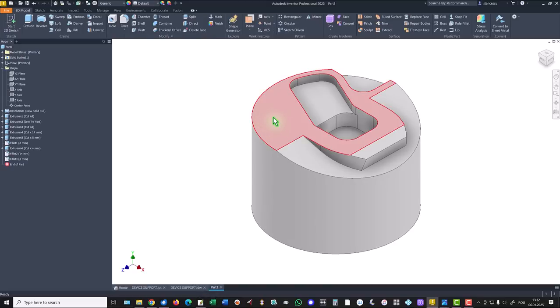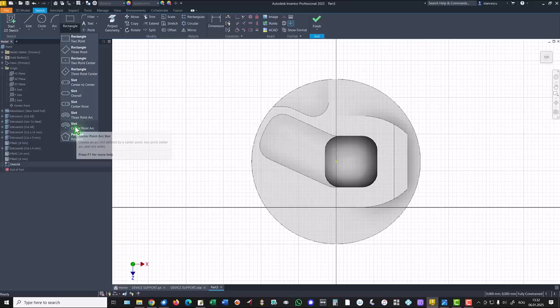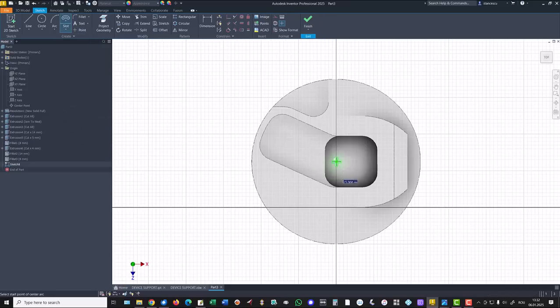Here is that new feature. We use curved slot with this center, the distance of 33, the radius of 33 from this point to this point, and so I draw a line from the center point to the center of this.